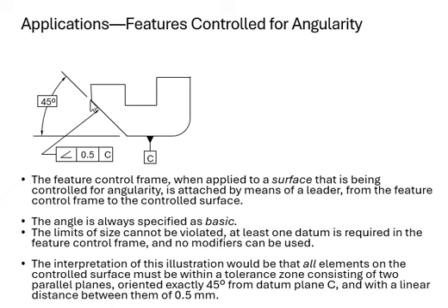Remember the two little yellow lines, showing you where this inclined surface is in between those two little yellow lines, okay? I drew these two little yellow lines right here for you. So we're talking about the parallel planes, because those parallel planes are imaginary for your tolerance zone.